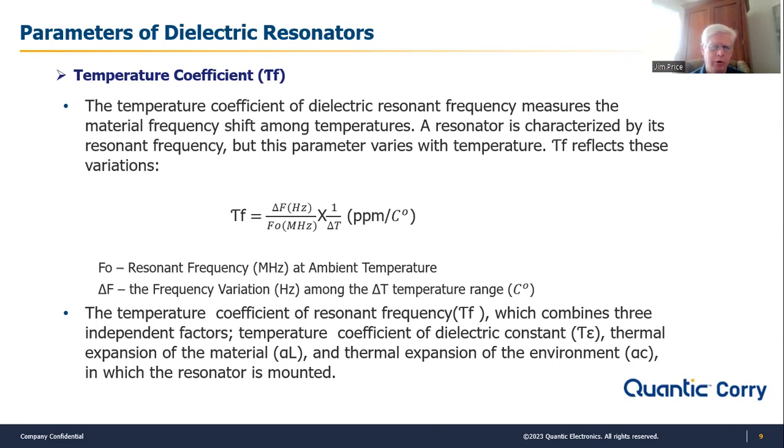And that's really important for narrow band and high frequency devices, because you don't want them drifting up or down in frequency, especially when your bandwidth is as narrow as it is with these devices, only a couple percent. If you drift a couple percent and the bandwidth's only a couple percent, you're not going to be passing anything that you're intending on passing. You'll be rejecting it.